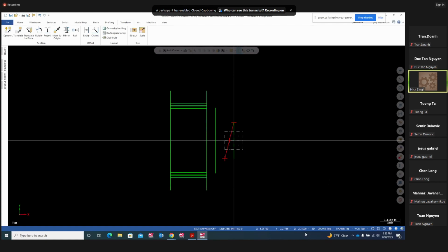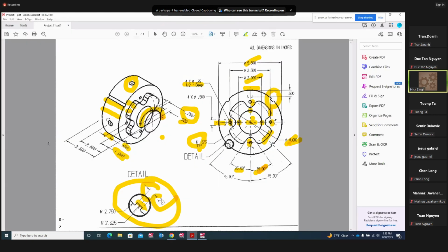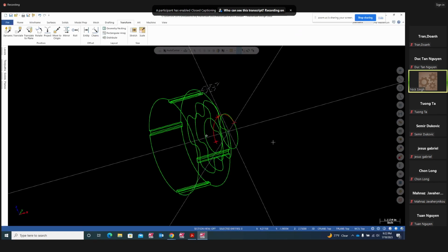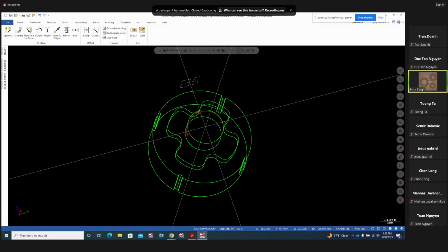And look at that hole right there, which is this same hole. So that is from the face 2.5. So when we draw that, we're going to draw that at x minus 2.5, y is going to be 0. But our z, look at that, our z has to be 2.75. That's where my z is at, 2.75.